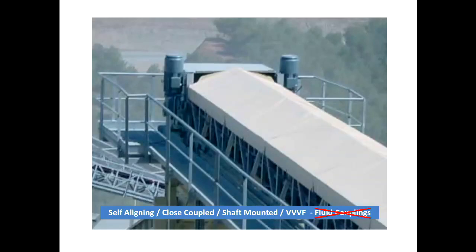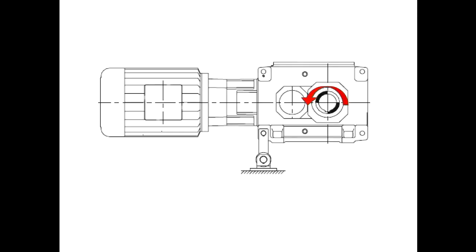And I like the motors mounted vertical, because when the fan blows air and brings in dust, it helps to keep the cooling fins on the motor clean, whereas a lot of people put the motors horizontally and they just fill up with muck. And fluid couplings, look, they went out with the ark. People still use fluid couplings a bit, but we've got VFDs now, that's variable frequency drives, so that's what you do. Okay, this is a problem, and this is one of the reasons why.